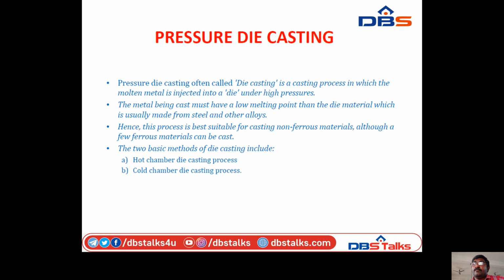Pressure die casting. Pressure die casting, often called die casting, is a casting process in which the molten metal is injected into the die under high pressure. The metal being cast must have a lower melting point than the die material, which is usually made from steel or other alloys. Hence, this process is best suited for casting non-ferrous metals, although a few ferrous metals can be cast.